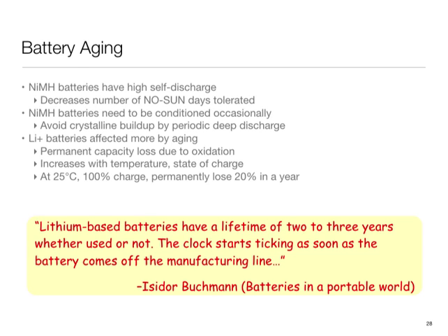Do you mind adding a little bit of information about lead acid batteries? Oh, it's so stale. Okay, lead acid. But they're still used. One reason lead acid is still used is that they are cheap. Another reason, particularly in developing countries, is that they're easy to replenish. To give you a sense, in my original home country, India, since the electric grid is awful, it is very common that we buy so-called inverters, which are basically DC to AC converters together with a big lead acid battery pack. When the battery begins to die, you put distilled water into it to rejuvenate it, and then you extend its life more. So they are easy, and unlike lithium, they are less harsh on the environment. They still have issues, but lithium has deeper issues. So those are the factors that come into play.